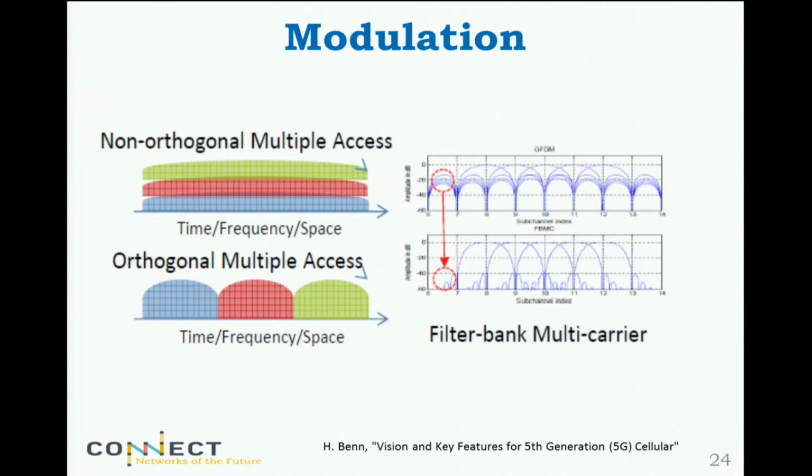So we go back to dear old OFDM, which has no problem whatsoever. It has been working forever with MIMO and massive MIMO, an easy extension. You just do your signal processing per subcarrier. So you do your MIMO design for one subcarrier, single carrier, many subcarriers, you don't care. It's always the same thing. You copycat what you do per subcarrier, period.